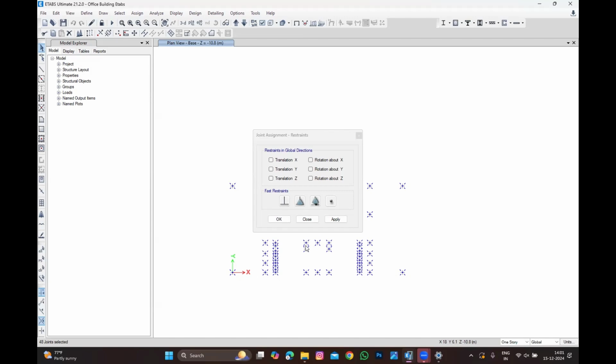But for a high-rise building, you don't need to worry, because since it is a raft, it is called finite element. Even if the moment is there, the whole plate is going to act against the moment. So there won't be any kind of overturning. But when you're talking about the individual foundation, the overturning will be very critical, because the individual foundation is a small piece, 2 meter by 2 meter, 3 meter by 3 meter, 6 meter by whatsoever it is, and that dimension is going to resist the overturning moment. This you will have a problem with.